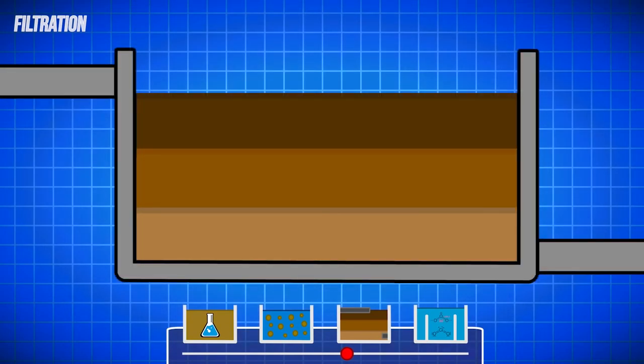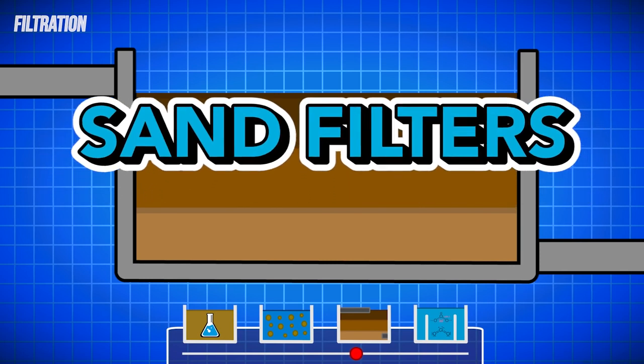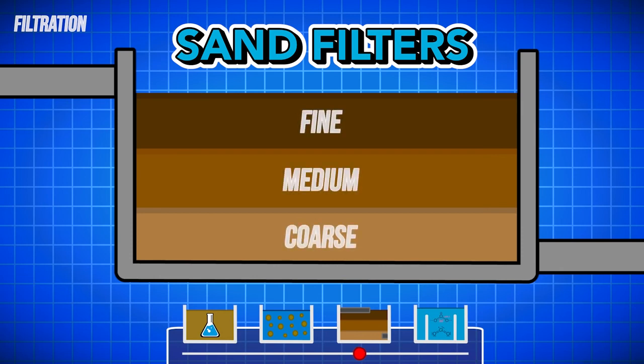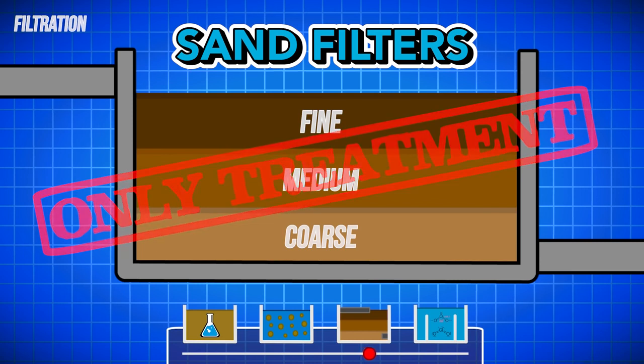Nearly every potable water treatment plant will use a sand filter for this process. Even in plants where engineers may not think it's needed, often sand filters will be added simply for extra measures to ensure clean water at the end. Sand filters are exactly what they sound like: a basin of fine to coarse sand that filters water. It would theoretically be possible to treat drinking water with only sand filters, but that would result in frequently clogged sand filters, resulting in lower efficiency and more cleaning time.